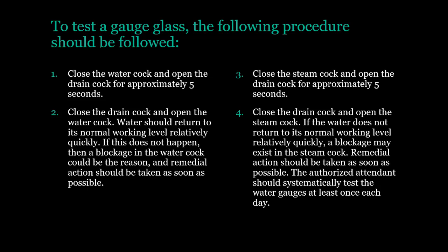Close the steam cock and open the drain cock for approximately 5 seconds. Close the drain cock and open the steam cock. If the water does not return to its normal working level relatively quickly, a blockage may exist in the steam cock. Remedial action should be taken as soon as possible. The authorized attendant should systematically test the water gauges at least once each day.